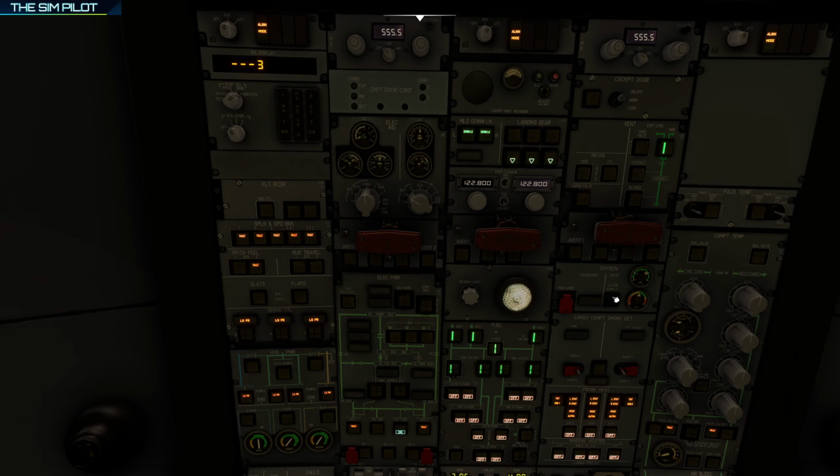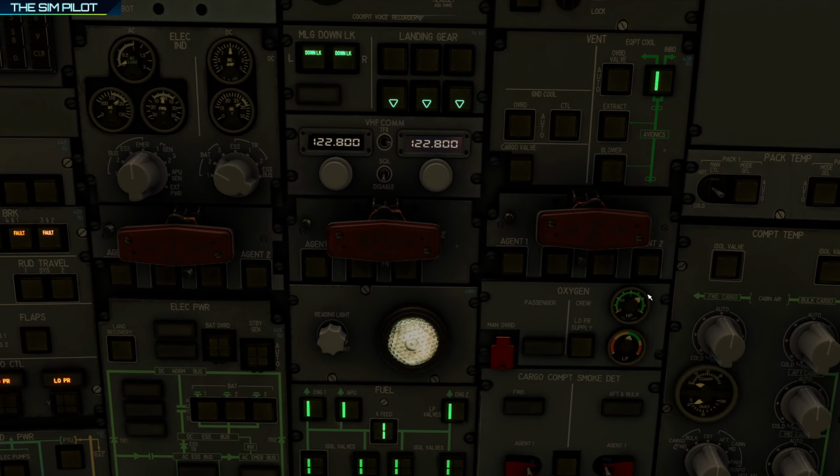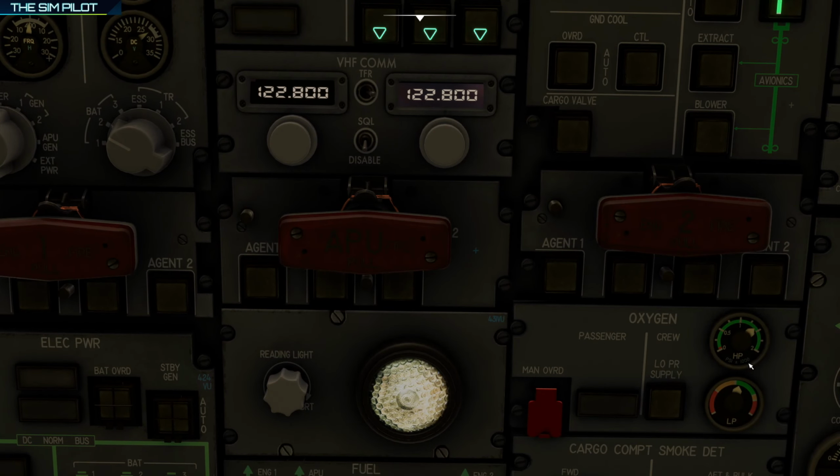We'll turn the oxygen system, or crew oxygen supply, on. This should read above 1400 psi, and the gauge is times 1000 psi, so that's 500, 1000, 1250, 1500, 750, and 2000. It is reading about 1250, close to 1400. That is within the limits.